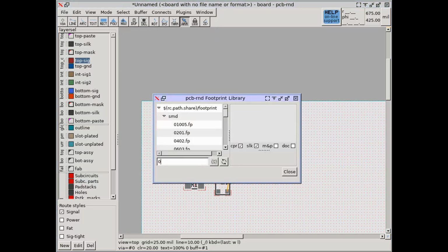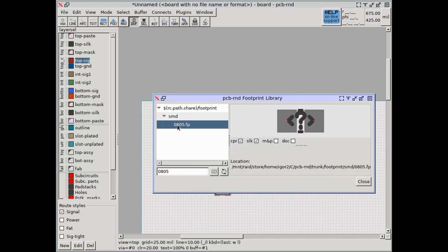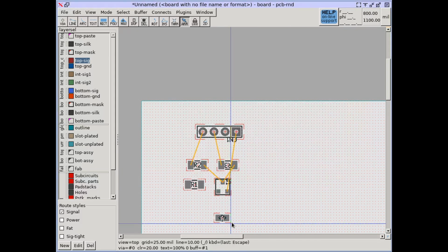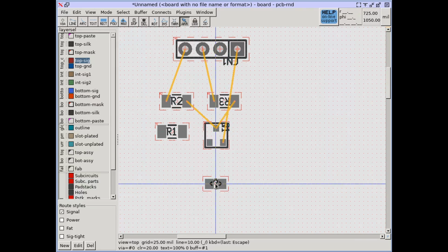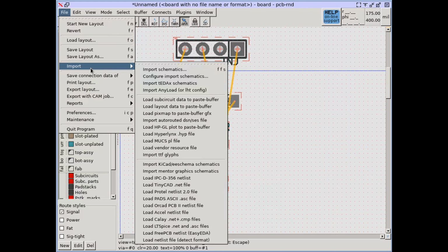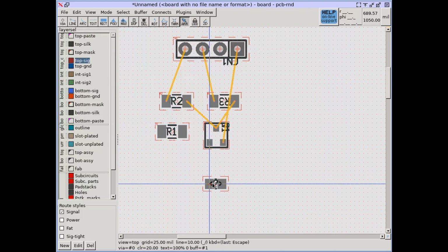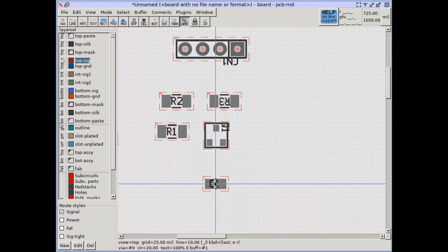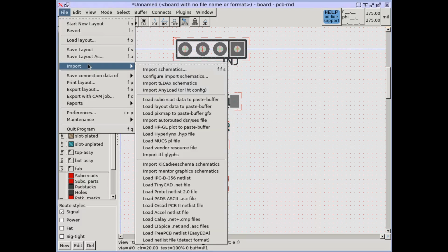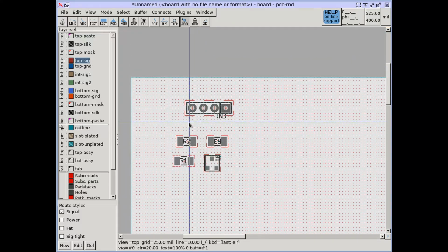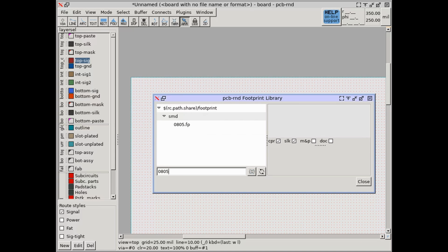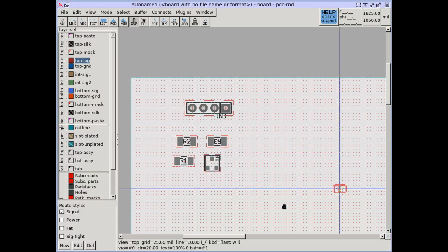In some rare cases, the designer may choose to place a footprint in PCB-RND directly from the library window without mentioning this on the schematics. If this subcircuit needs to be in the BOM list and XY files, it needs to have a valid refdes. A typical example is a 0 ohm SMD resistor used for routing as jumper on a 1 or 2 layer board. To avoid a netlist import removing this subcircuit, set its No Netlist flag to 1.